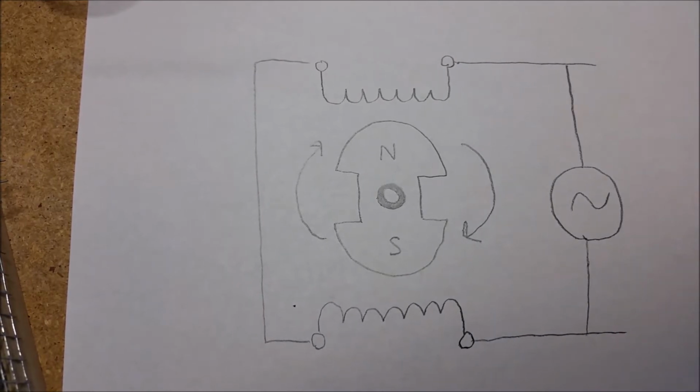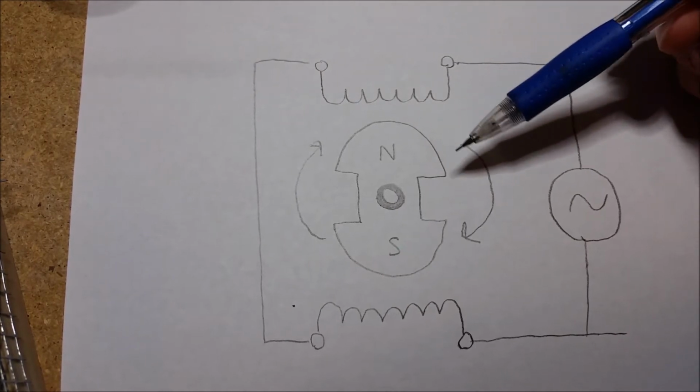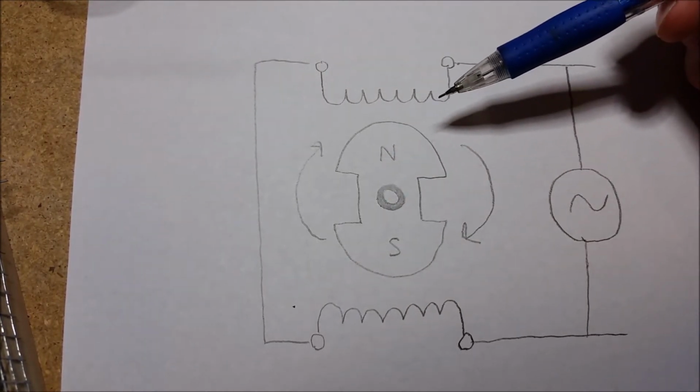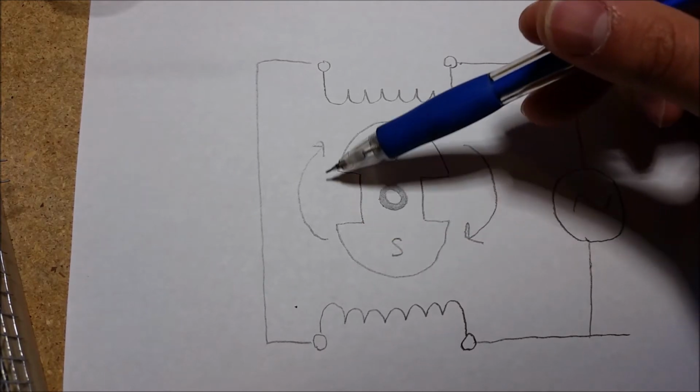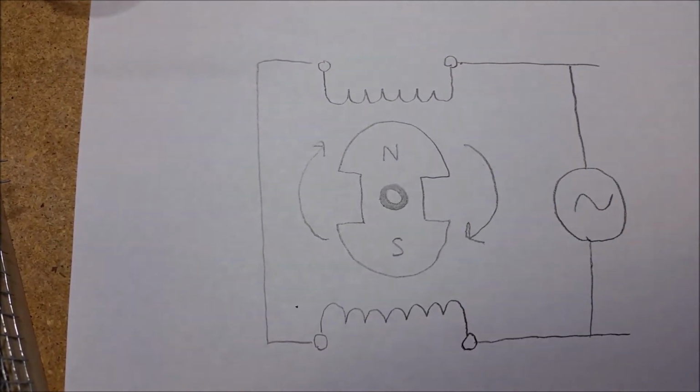Unlike DC sources like batteries or commutated generators, AC is generated by rotating a magnetic field with respect to conductors. And so if you turn a magnet like this, with respect to copper coils, an AC voltage is induced in the conductors.